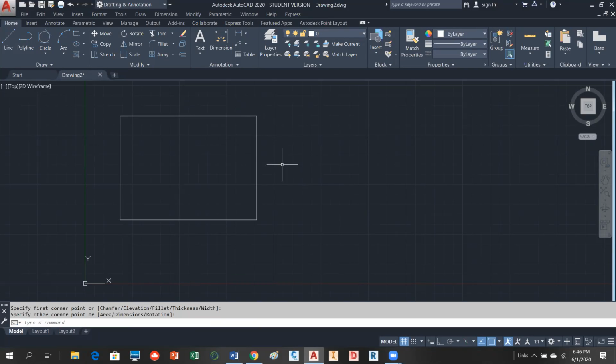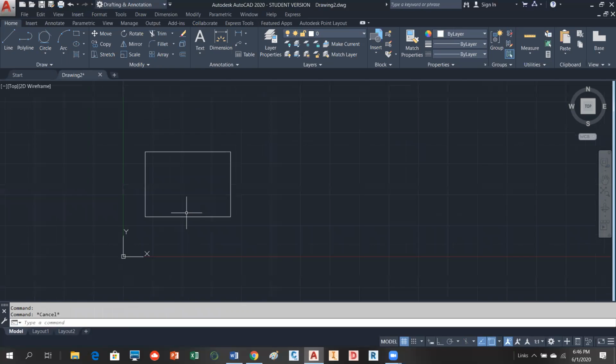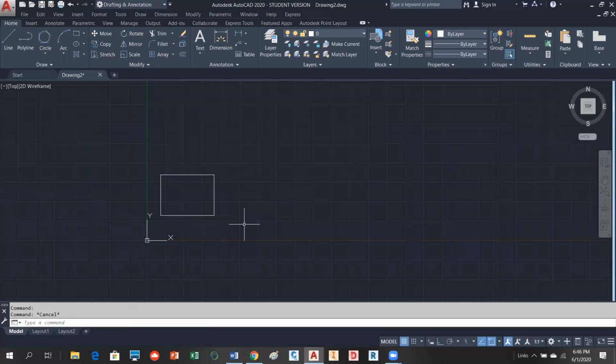If you click on this thing, you will notice that it is all one object, okay? Unlike if you did that with 4 lines, you would have 4 objects. With this type of object, this polyline, what you have is one object, okay? Somebody get that to work? If you selected it like I did, just go ahead and hit the escape key, and you can keep it as an intact object.